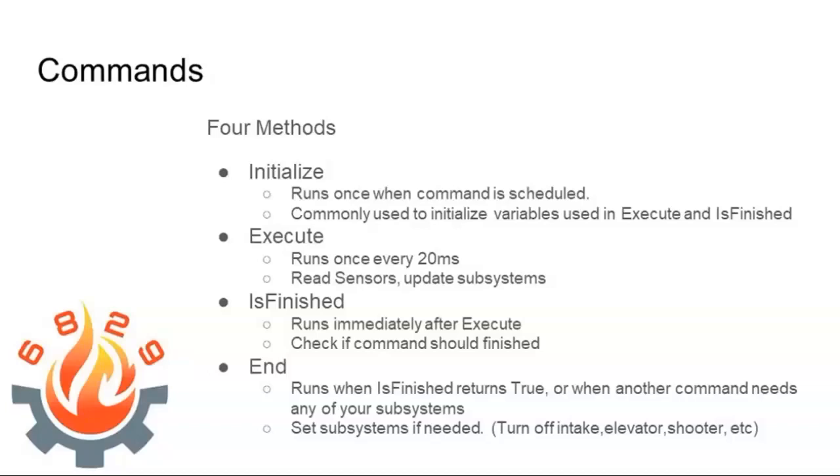and talking to the subsystem. Is finished is the WPILib framework asking you, are you done running yet? Have you reached your goal? If you're trying to drive forward 5 feet, the code inside is finished should be a simple check. My encoder value needs to be 5,000.